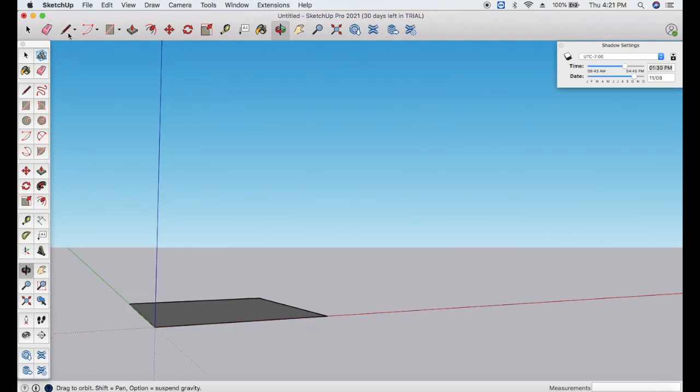Now, if we want to form coplanar drawings or coplanar rectangles with this, how can we do it? We can take the drawing tool, pencil. We can go to the endpoint. In the endpoint, it will show as a green dot. Whenever we are at the midpoint, it will show as a blue dot, green dot for the endpoint, and any other points or the edge will be represented as a red rectangle. So endpoint is green dot, midpoint is blue dot, and any other points on the edge are represented as a red rectangle.